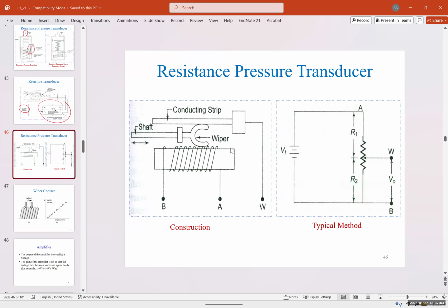Another problem, if you have very high voltage or very high current passing through these, it's going to work like a welding. You have a lot of sparks and it's going to weld them together. If you have had any of these drills that use a regular DC, not the brushless DC, and you look at the back, it's going to create these sparks. And the commutator, if you don't replace those, is going to eventually wear out and destroy the motor. So that's a little problem.